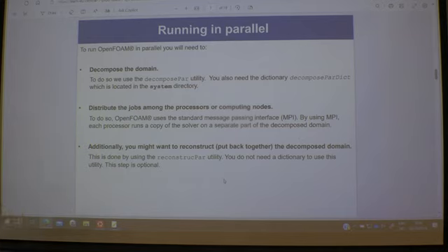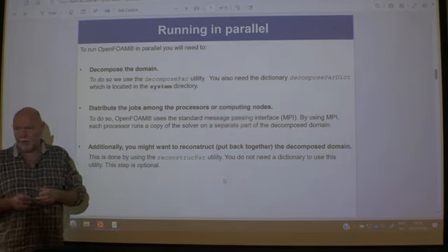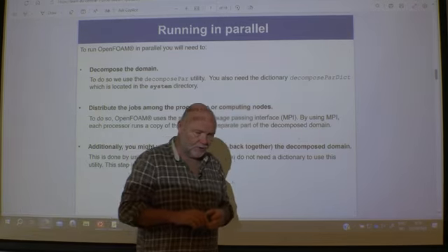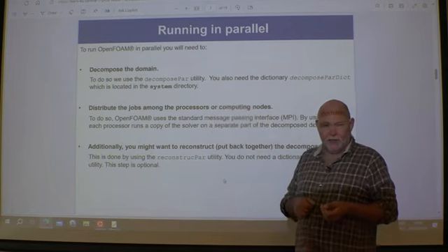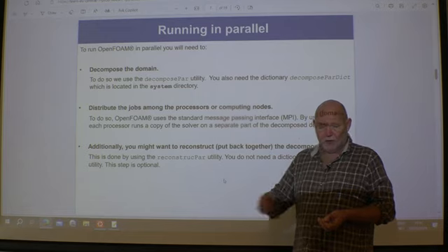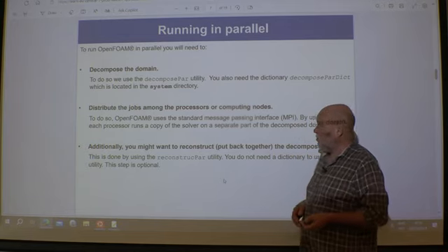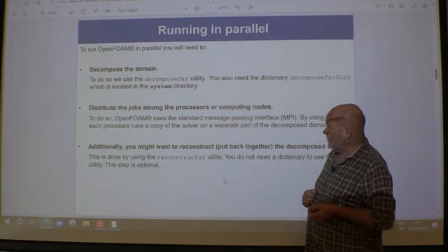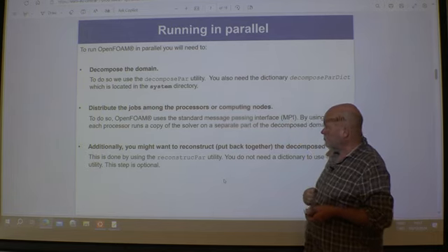To run in parallel, you have to do some additional steps. First, split up your domain. And when I say split up, not just logically, this is physical. So you tell the setup, we split it in, say, 4, and then you need 4 CPUs to deal with each of their own subdomains and calculate everything there. So that is what decompose means.